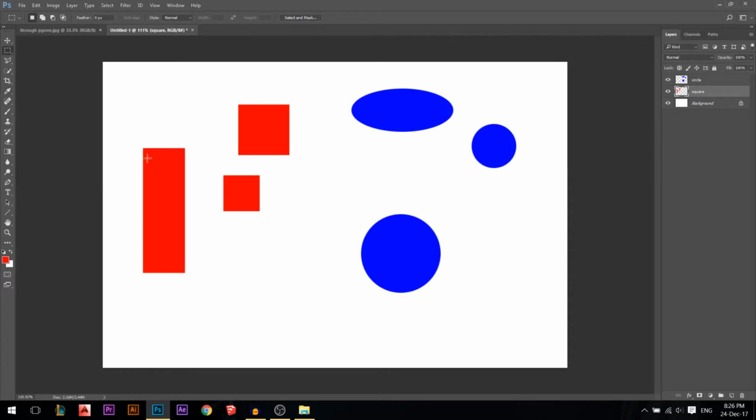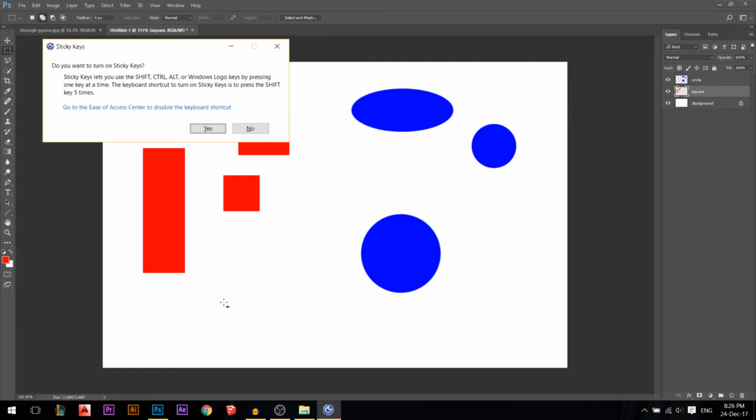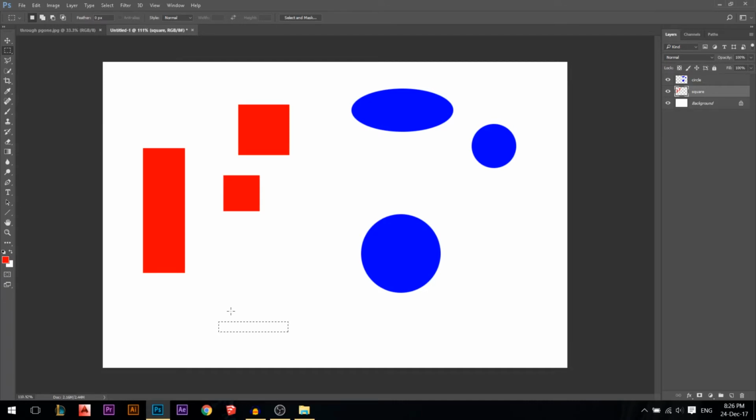Now I don't want to make just one selection, I want to make an L letter. To make that, I'm going to make my first selection. Now I want to add another selection to it to make the L. If I add the rest of the selection like that, the first one will disappear. So before pressing click, I'm going to press Shift. You see what happens when you press Shift? A small plus is drawn next to your mouse. So I'll press Shift and then click from here and pull. Now I made two selections forming the letter L, then I press Alt Backspace.